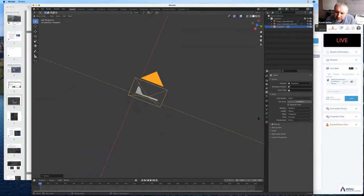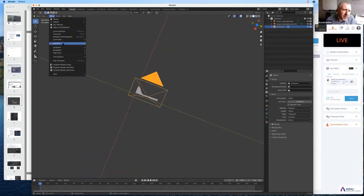Now, if the camera is selected, you see a little camera icon appears here. If the geometry is selected, a little mesh icon appears. So the camera is selected, and the camera is now our active object. That was Command-0, or you can go up to your View menu, Cameras, and Set Active Object as Camera. That's the other way to do it as well. There's lots of things in the menus up here.